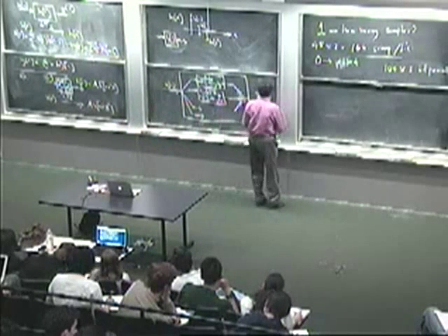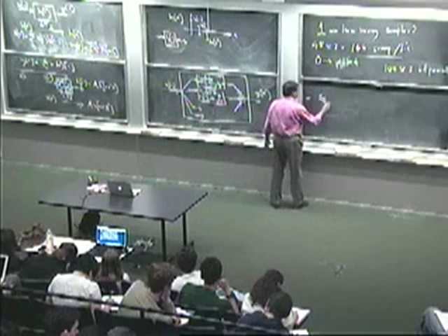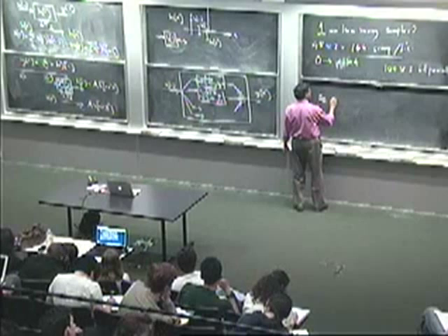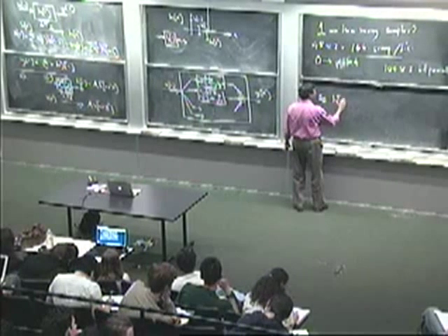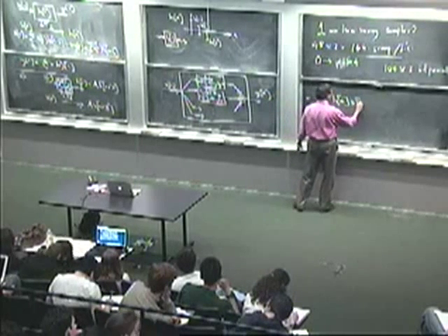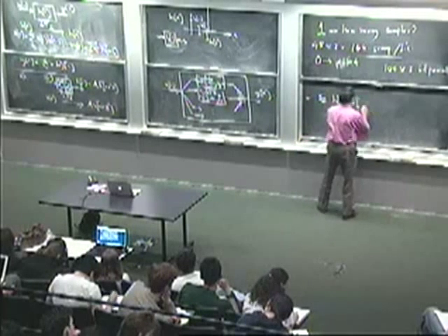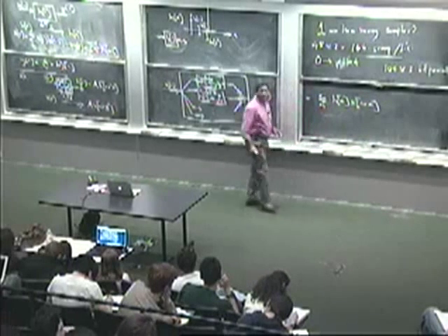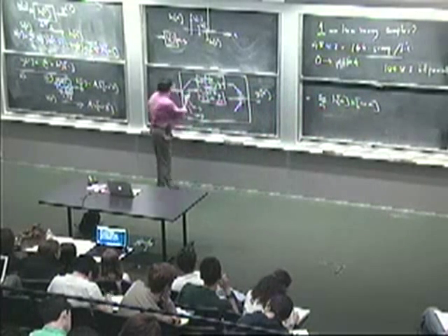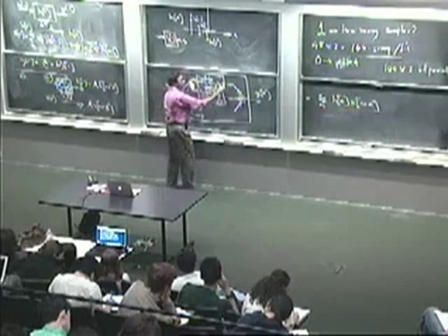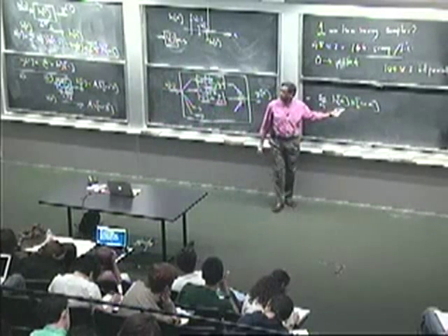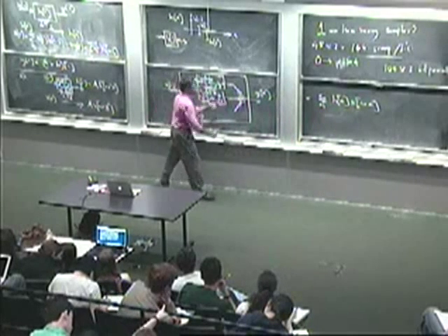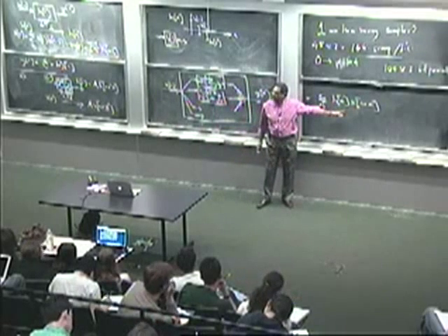So what comes out, y of n, is equal to the sum of h[m] x of n minus m over all m. Okay? So I take x[n], I shift it by nothing, I scale by h0, that's the term corresponding to m equals 0. I take x[n], scale it by h1, delay by 1, that gives me the term with m equals 1.